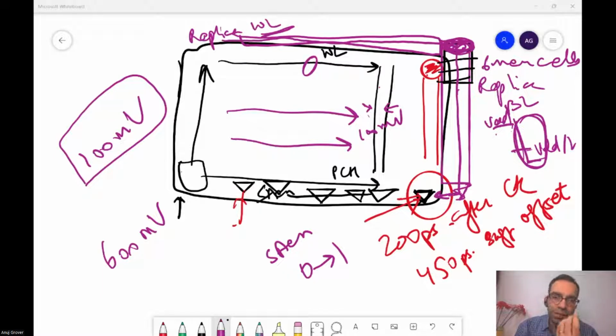The problem is that the typical conventional latch type sense amplifiers that we have, they need an SAEN signal which is digital in nature, which goes from 0 to VDD. That is when the tail transistor will sink sufficient current to trigger something. So the digital signal is 1 volt and 0.6 is differing between 0 and 1, right? Yeah. Now got it. Okay. 0.6 is just a representative number. You may say that I want to discharge it by 1 volt or by 0.9 volts, and then it will trigger the sense amplifier.